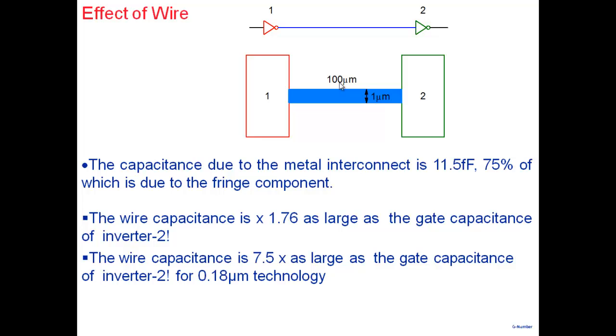Whether an AND gate will work as an AND gate, fine. Whether a flip-flop will work as a flip-flop, you can do that. But at what speed can I run my flip-flop? At what speed can I run my multiplier? For all those other things, you have to do the layout, extract it, and add all the capacitances there. Without that, you simply cannot. You will have all wrong estimates.